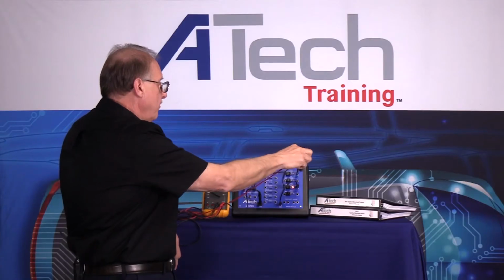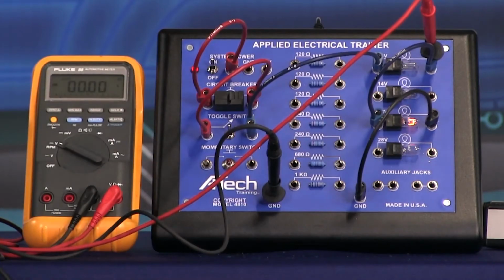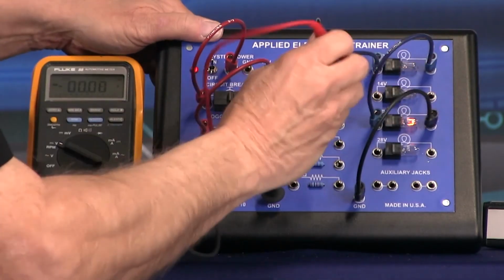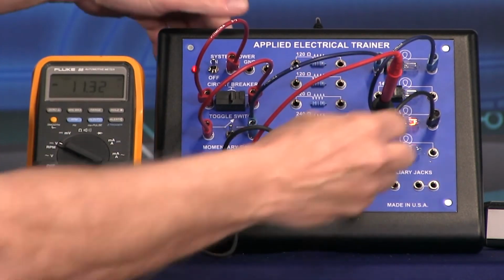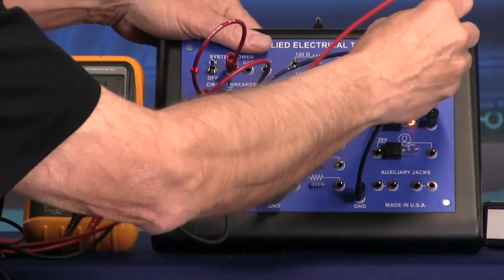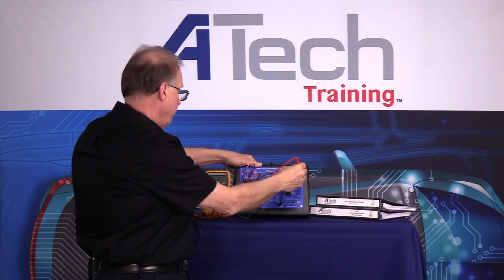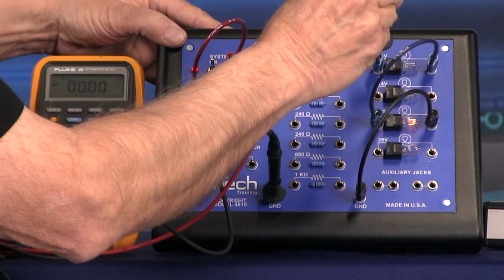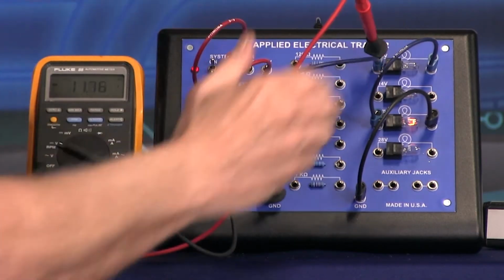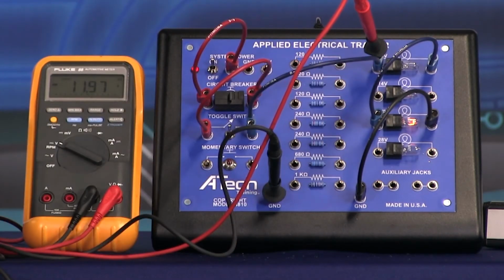If I go after this one, it doesn't look like I'm using much voltage at all on that point. If I go back over here to the next one, 11.32. Honestly, I've got a little bad connection right now. 11.32 right there after it, and I had 11.97 before it. So I can actually voltage drop each individual component to see if it's working properly.